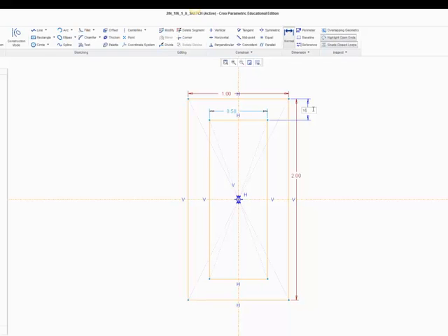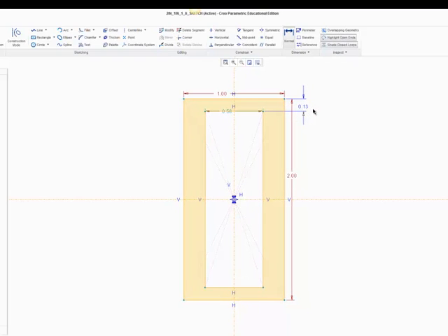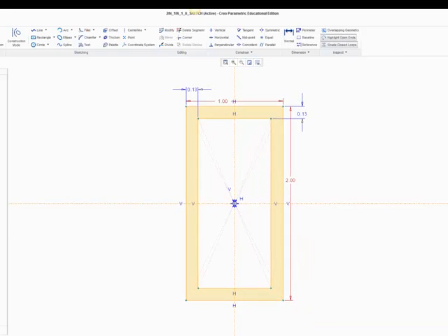So I'm going to hit 1/8. Now Creo does all the math for you, so you don't need to get a calculator out. Just input the formula, hit enter, and the math's already done. Notice that I'm still in the normal tool, so this is 1/8 thickness, but this still needs to be the same distance as that. So I can click, and then mouse wheel right here, same dimension pops up, 1/8, perfect, select.